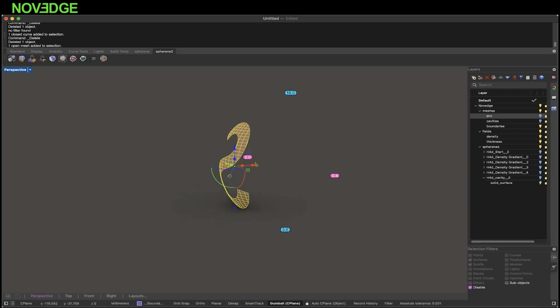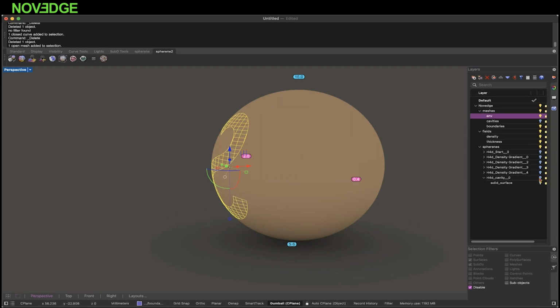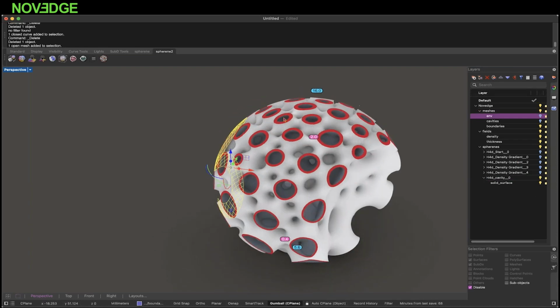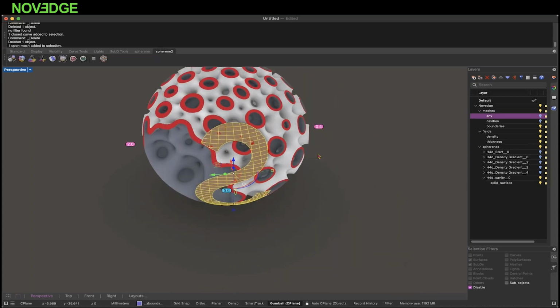First, let's keep it simple. We want a hull thickness. We want to thicken this up. So that's this one, hull thickness. We thicken it up to 1.2 millimeters. Then the target thickness, that is when we have the Spherene structure. So you see, we changed the thickness using these two field points.